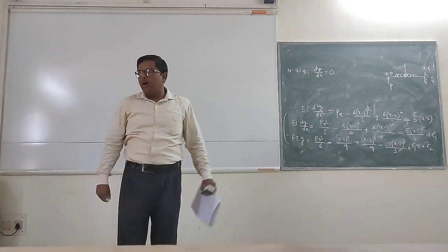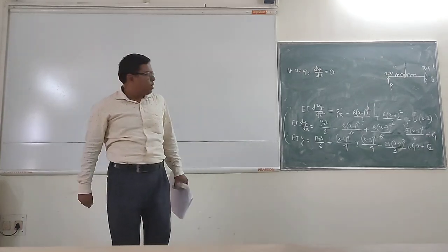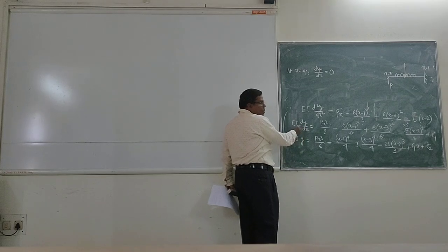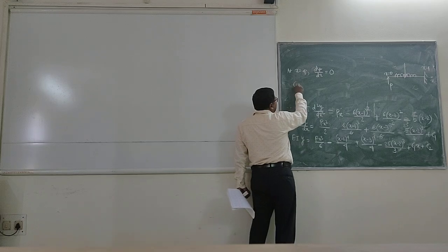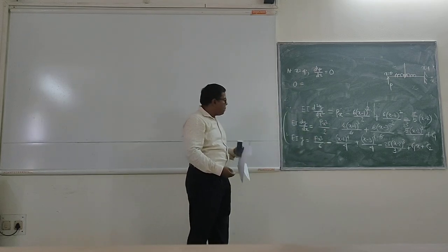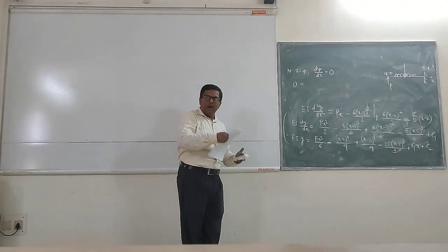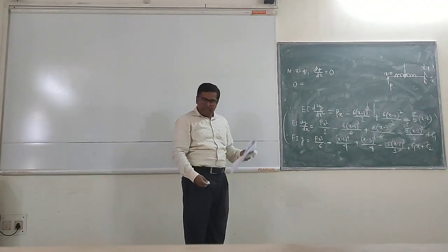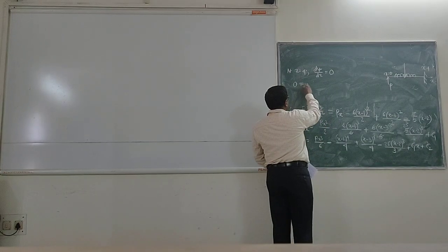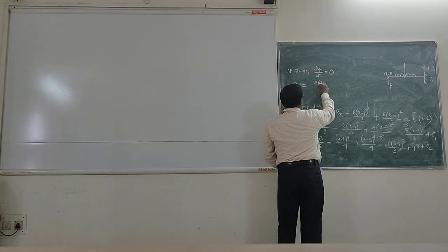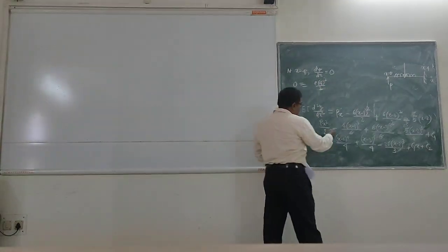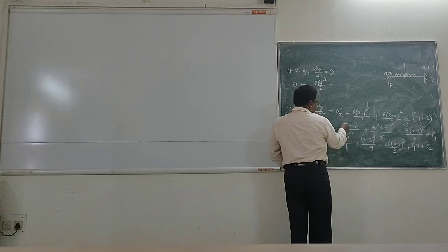So put the condition and you get one equation. So at x equal to 4, dy/dx equal to 0. So I put dy/dx equal to 0, so 0 is equal to P x square by 2. So what will happen to P x square? x is equal to 4, so it will be P 4 square by 2, right? Correct? Next will come minus, this 6 is cancelled, right?